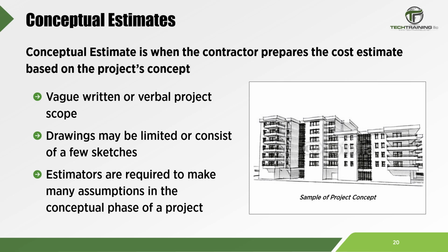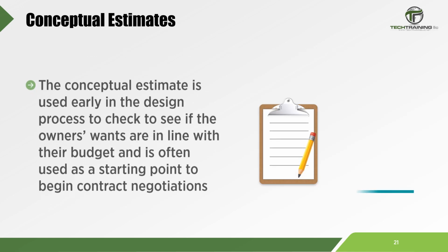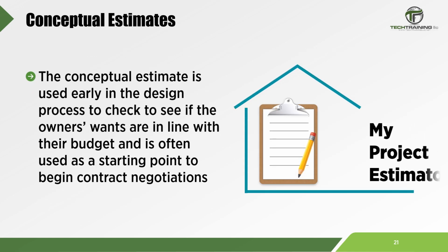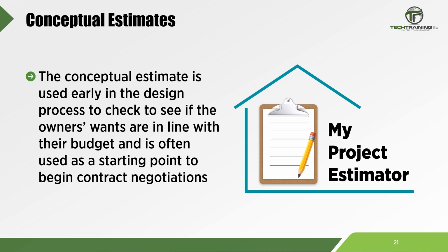In conceptual estimates, historical data becomes priceless. The conceptual estimate is used early in the design process to check to see if the owner's wants are in line with their budget and is often used as a starting point to begin contract negotiations.